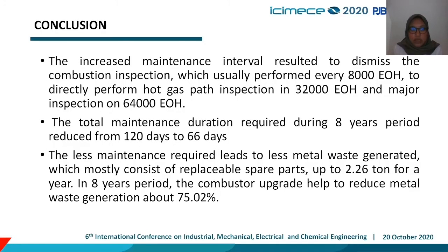The conclusion: the increased maintenance interval resulted in dismissing the combustion inspection, which is usually performed every 8,000 hours, to directly perform hot gas path inspection at 32,000 hours and major inspection at 64,000 hours. The total maintenance duration required during an 8 years period is reduced from 120 days to 66 days.